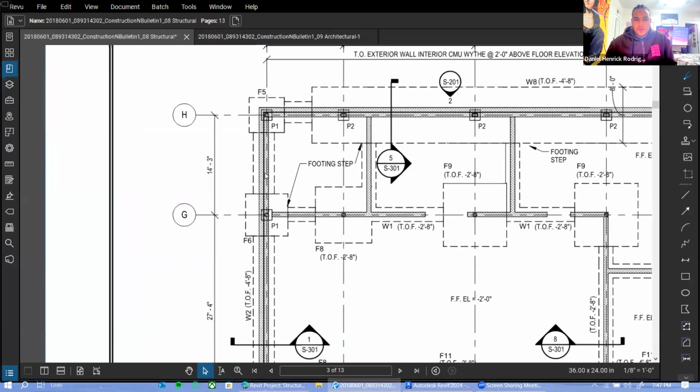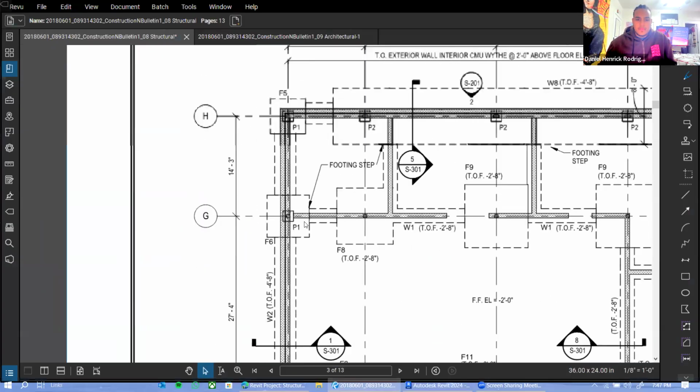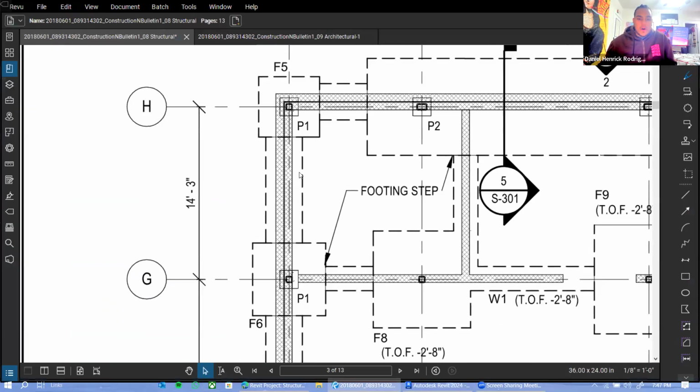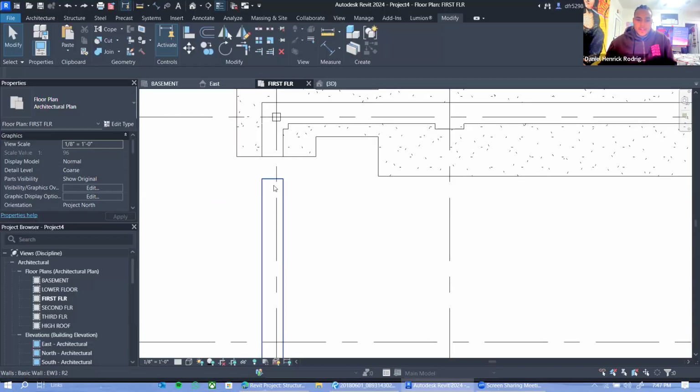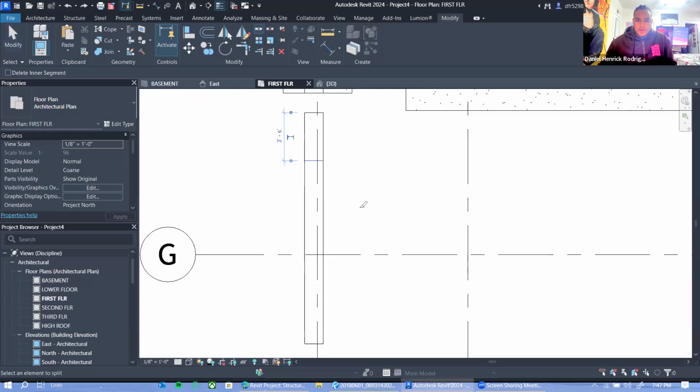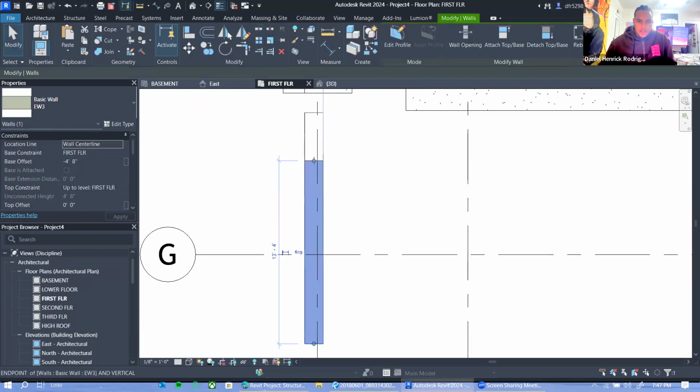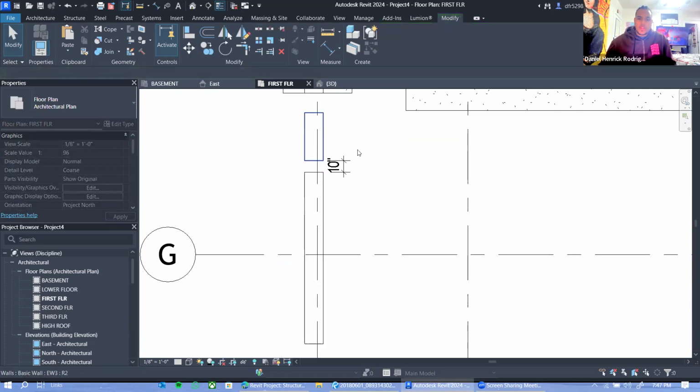I know on the drawing that I'm gonna go from this wall footer to another isolated footer. So I'm actually going to create another separation here. Doesn't matter where, honestly. As long as you have an isolated wall, you can do with it what you need, and then deal with connecting it later.